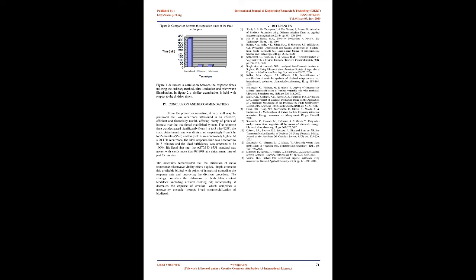At a 20 kHz frequency, the optimal reaction time was found to be 5 minutes and the optimal amplitude was found to be 100%. Biodiesel that met the ASTM D6751 standard was obtained with yields more than 98 to 99% at a separation time of just 25 minutes.